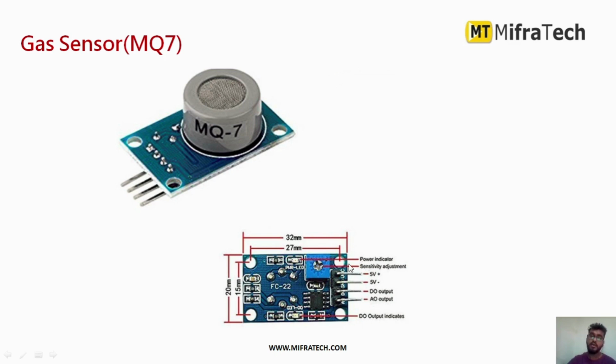Whenever we provide power supply to the gas sensor, the power LED turns on, and whenever we detect combustible gases, the D out output LED glows. The total length is 32 mm and the width is 20 mm. So these are the different components present in this MQ7 gas sensor.